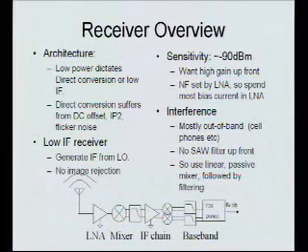But the second problem is that it's harder to filter, so you're going to actually have to handle more interference, and so you'll also need more bits on your ADC. So it's a double whammy. Probably you have to go faster, and you also have to have 3 or 4 more bits of resolution to handle all those interferers you couldn't filter. So in this case, we went all the way to baseband.